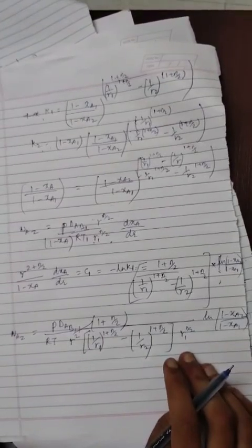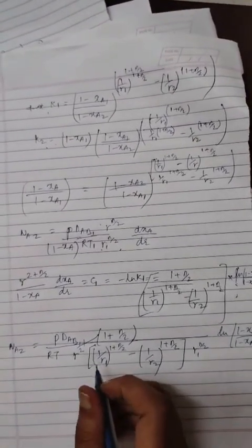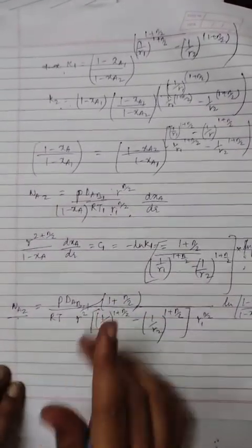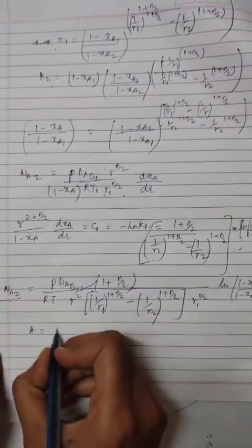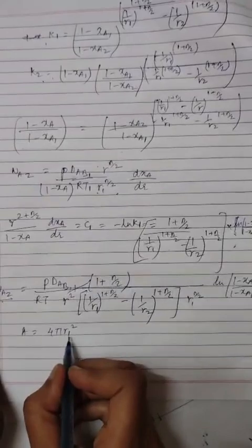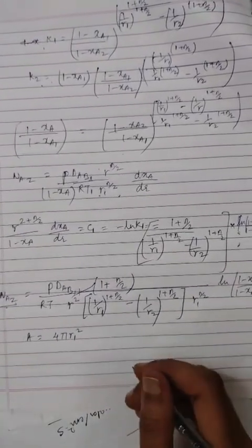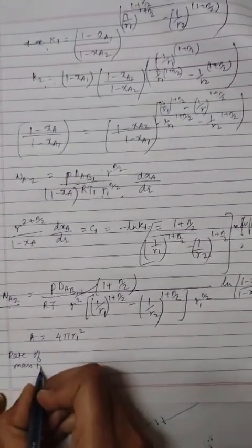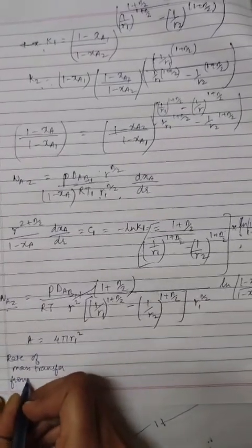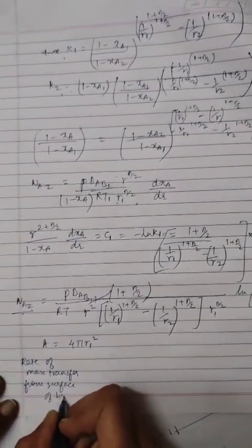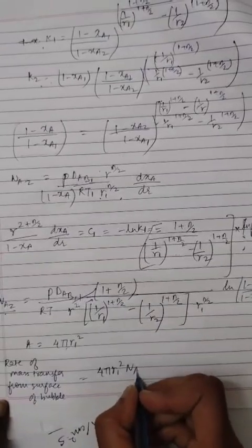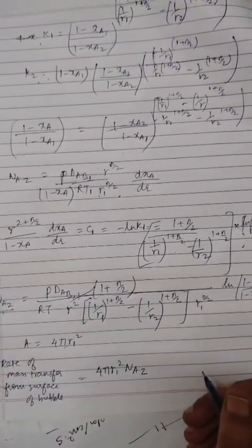Now, rate of mass transfer from the surface of the bubble, if we want to find, we will have to multiply the flux into area. Now area would be 4 pi r1 square, since r1 is the radius of the liquid droplet. So the rate of mass transfer from the surface of the bubble would be area into NAZ, 4 pi r1 square into NAZ, which will give us the final equation as,